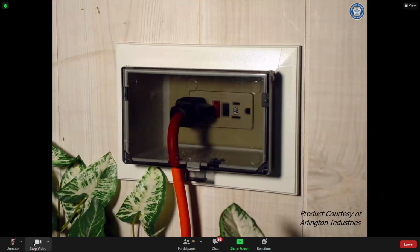Manufacturers have stepped up to the plate, and here's one by Arlington Industries that only extends from the wall less than half an inch. But it's still an in-use cover that provides weatherproof protection, whether or not a cord cap is plugged in or not. The receptacle itself is recessed in this case. So yes, that would be code compliant as well. And there's your WR